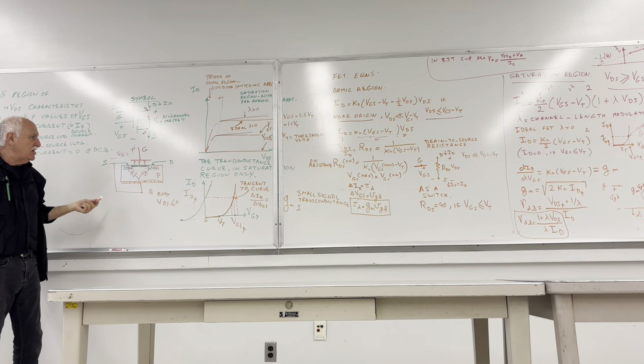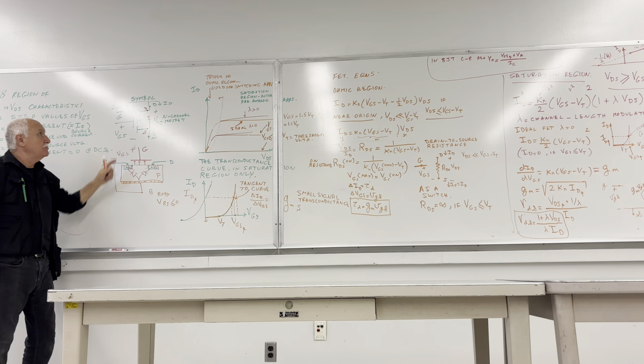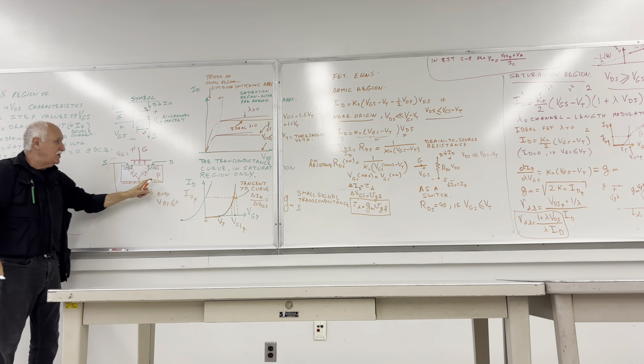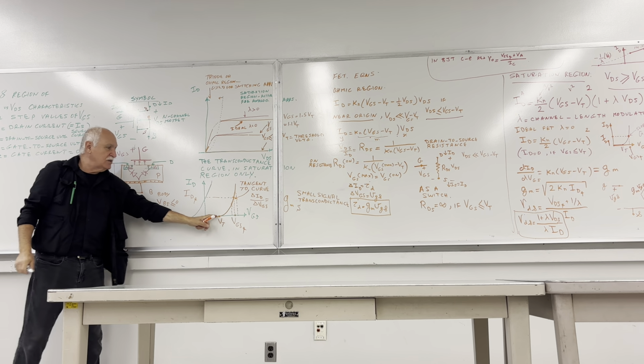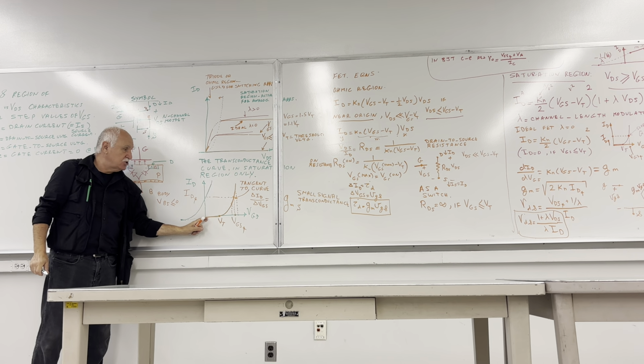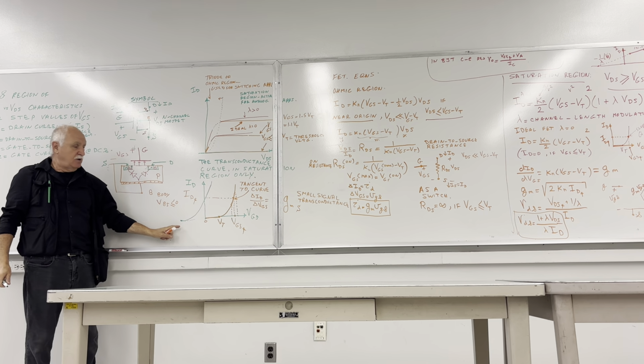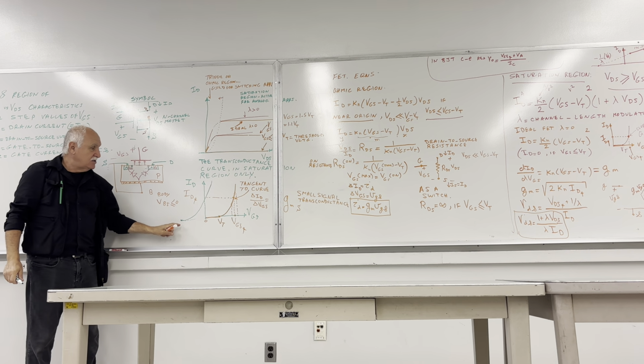For digital devices, this one is perfect. So that below a threshold level, there will be no conduction. And it is logic compatible because all voltages are 0 to positive. This one is not logic compatible because voltages are negative going to the positive.